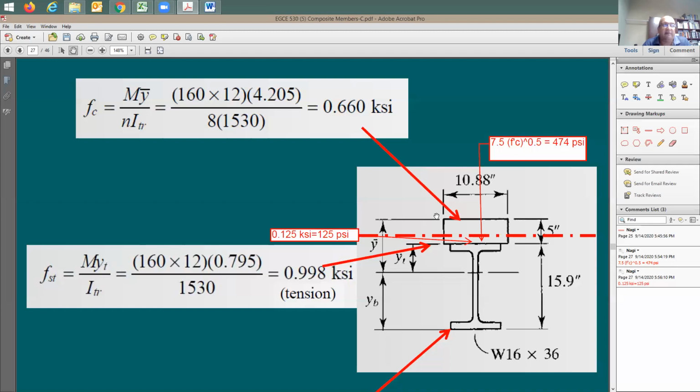Now you'd like to bring it back to the fact that it is made out of concrete, and the stress here is kind of overestimated, right? So you need to bring it back to the original value of the stress in concrete. This is why you need to divide it by n, which is the modular ratio between Es and Ec. Oh, okay, that makes sense. Okay. Thank you. Great, no problem. Good question, Mike.